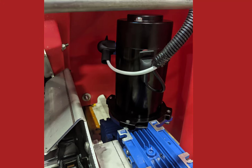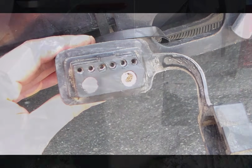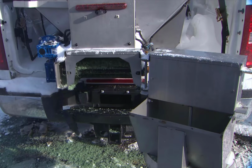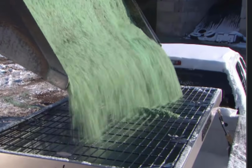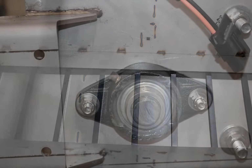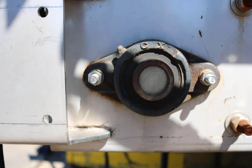First, check all the connections for any loose, corroded, or chafed wiring at both the motor and the spreader module, as well as the truck and spreader side harness. Inspect the conveyor and ensure that there is no jammed material. If the hopper is full of material, you may have to empty the hopper manually in order to check for jammed material and ensure that there is no damage to the conveyor chain. Check the bearings for proper greasing and ensure no bearings are seized.